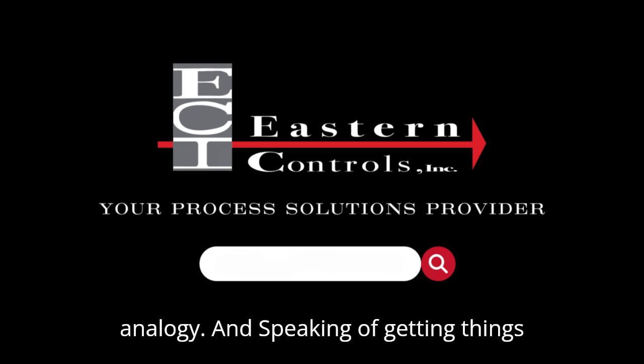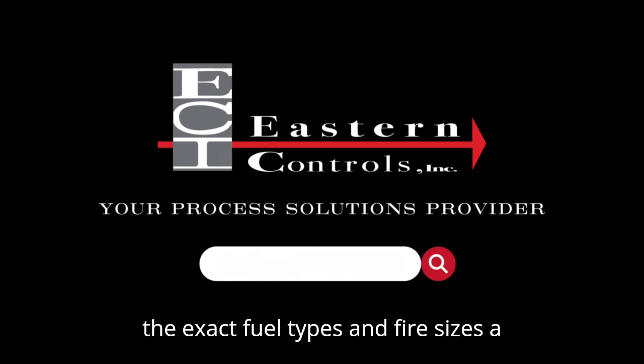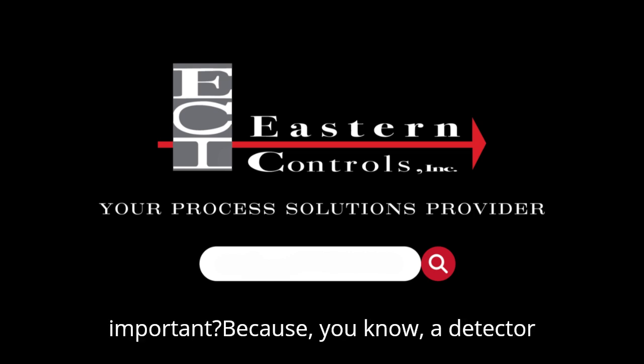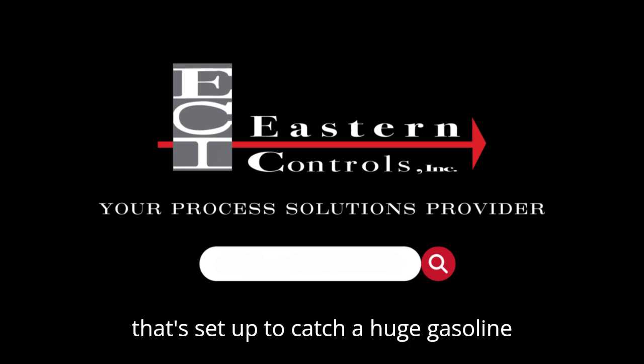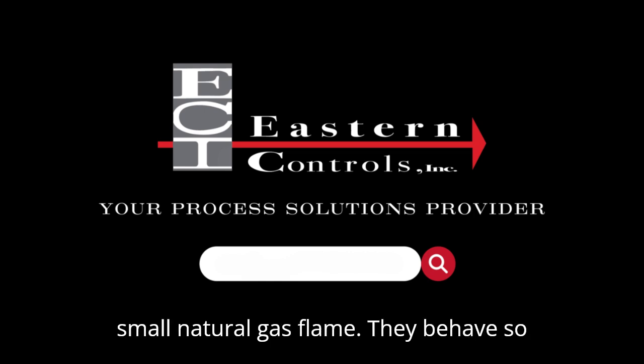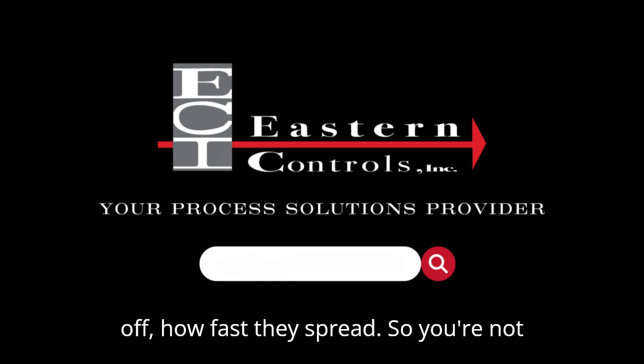Perfect analogy. And speaking of getting things right, our source really stressed knowing the exact fuel types and fire sizes a system needs to handle. Why is that so important? Because a detector that's set up to catch a huge gasoline fire might not even register a small natural gas flame. They behave so differently. The heat signatures are different, how much radiation they put off, how fast they spread.